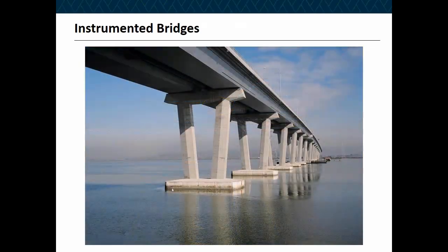Here is another example of an instrumented bridge. You can see again, the pile caps are very massive, and therefore they need to be included as part of your foundation and superstructure model, and that's why we need to use computer programs such as Midas and other computer programs that have the capability of doing a direct model, which means including the piles, pile caps, and superstructure within the model. And I will explain it as we go further along.